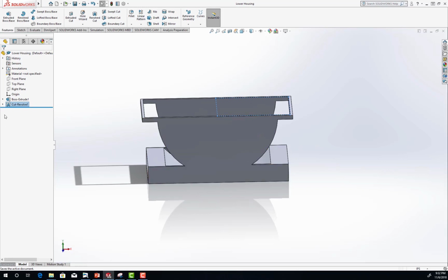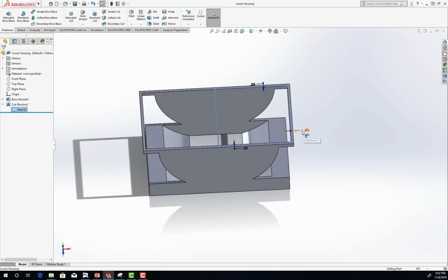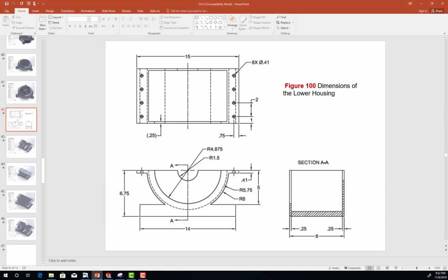Then let's go to the sketch tool and figure out the thickness here. So go back to the PowerPoint. So this is, oh, okay, this is a 15 at the top. So it's a 15, and the inner one is 6, so the diameter is 12. So 15 minus 12 is 3, so means each of this is 1.5. So let's add 1.5 on top of a quarter. So remember we put a quarter there.